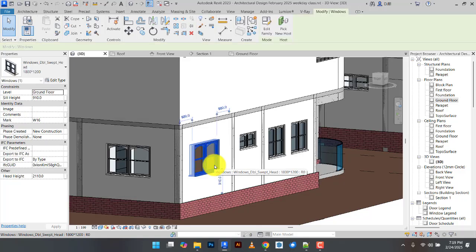If you are lucky, there are some window families that come with those moldings. That one's excellent. Just select it and use it. Now when you change the size, it still comes with the design. As much as possible, look for those families and use them, and don't worry yourself about creating it. I can tell you it's a waste of time.